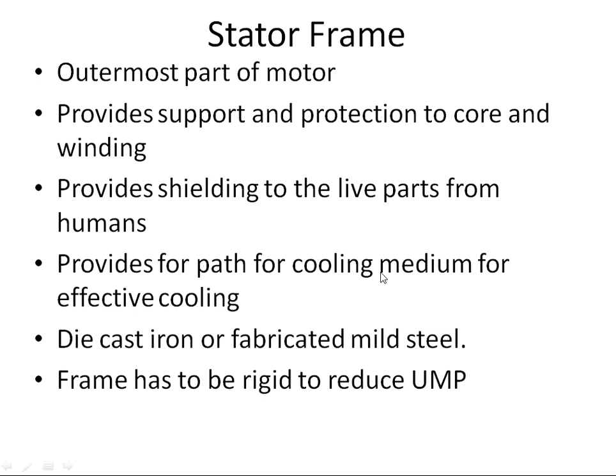It also provides a path for the cooling medium for effective cooling, so air ventilation is required so that the motor remains within its limited temperature range. The fan will be providing the cooling, but the stator frame consists of axial ventilating ducts, or it may have radial ventilating ducts. These ducts will have a flow of air through them. So the stator frame provides a sufficient path for this particular flow of air.